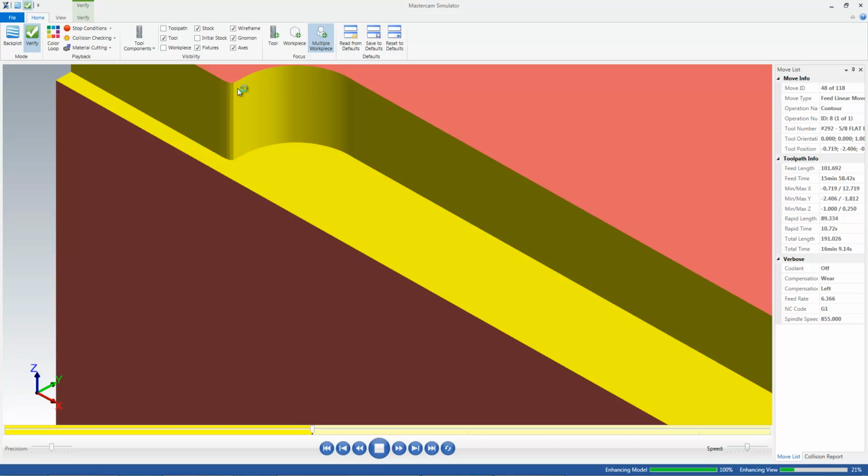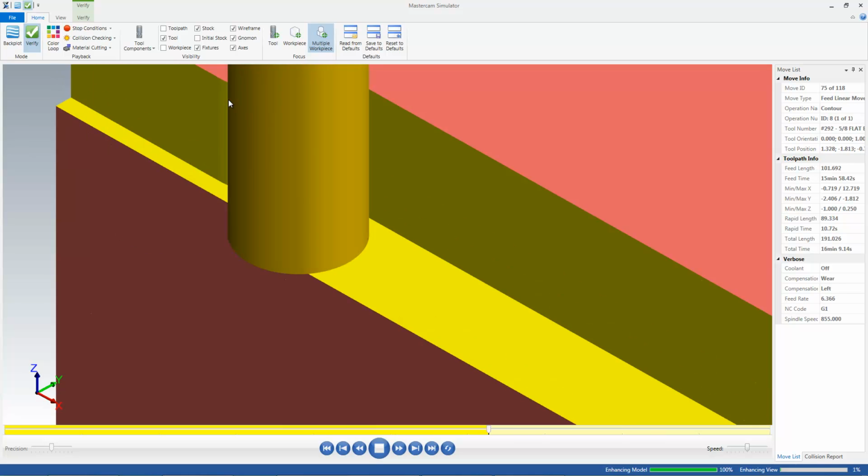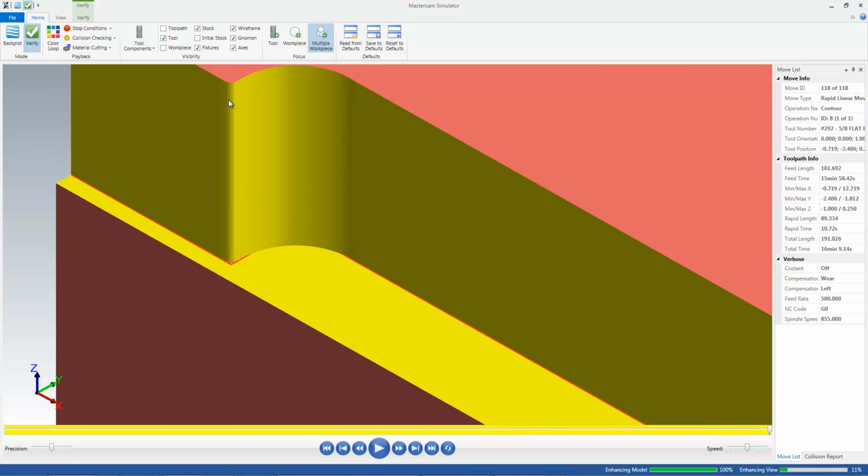And you can see how it's forming that radius there on that end, and it's rolling over that end to form that 30 thou radius. So that's two good ways to control your tool in an internal corner and an external corner.